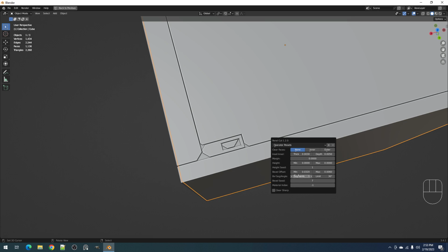And also using the bevel, if the values go past 0, the merge option is no longer there as well. And we have the bevel segments, increase the segments of the bevel, and the angle limit. So it's much like using the bevel modifier. And we have the bevel seed, that's to randomize material index to inherit the material from the source mesh.